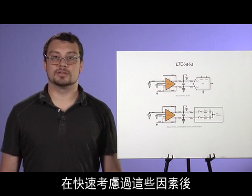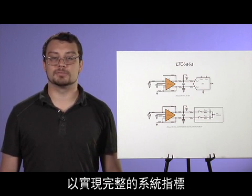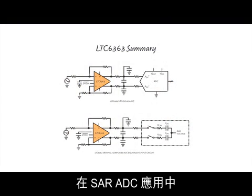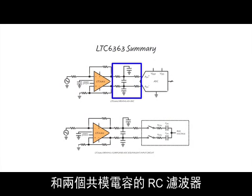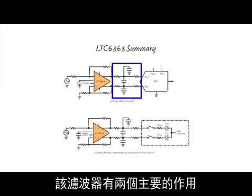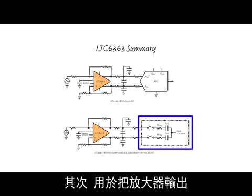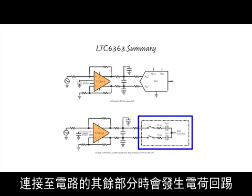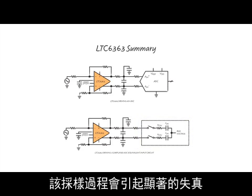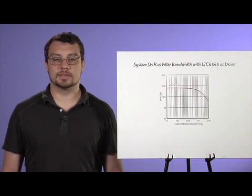After these quick considerations, the designer must pay close attention to the interface between the driver and the ADC to achieve full system specifications. In SAR ADC applications, the typical interface filter is an RC filter with a differential capacitor and two common mode capacitors. This filter serves two primary purposes. First, to band limit the noise of the amplifier and the resistors. Second, to isolate the amplifier outputs from the charge kickback from the ADC, which occurs whenever the ADC switches connect the sample capacitors to the rest of the circuit. Without a carefully designed filter, this sample event can cause significant distortion. Before I demonstrate this, let's first look at band limiting noise.